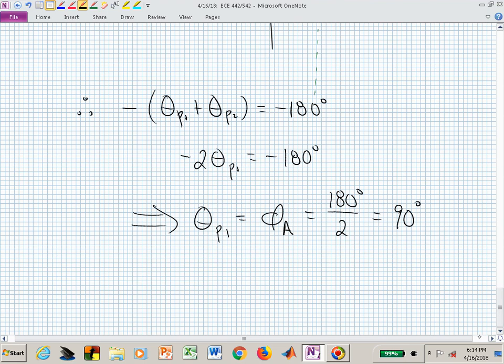So far, far away, that three-pole, one-zero pattern looks like a two-pole system with the asymptotic behavior determined by the centroid of those two approximate poles and their asymptotes, which are at plus and minus 90 degrees, or 90 and 270.